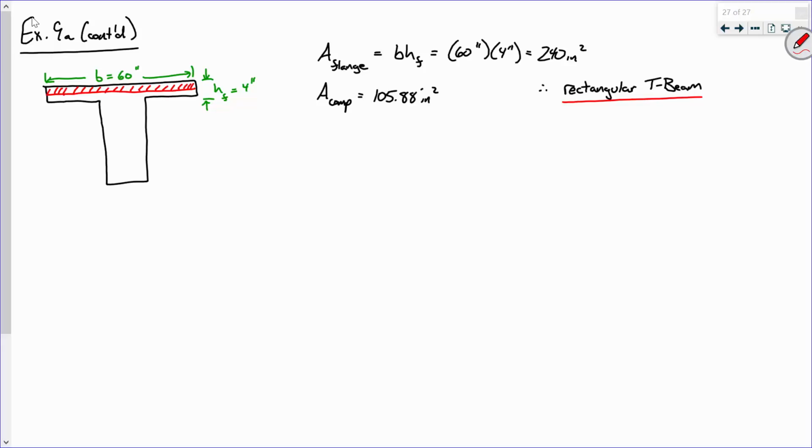Yes, exactly right. If you put loads on that, would the area of compression change? No. We're talking about ultimate capacity. We're talking about what the beam can supply, okay? And the ultimate capacity of the beam has nothing to do with the loads. It has to do with C equals T, okay? That isn't affected by the loads that are on it. It's a good point to make, but it doesn't affect this, all right? Everybody okay with this?